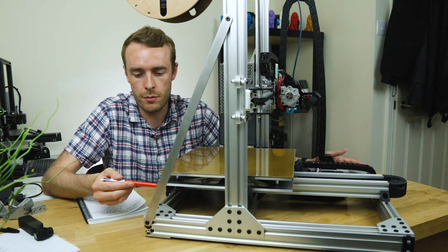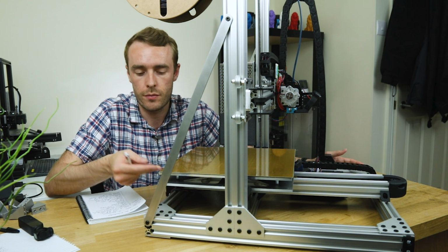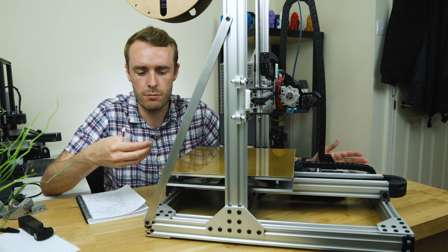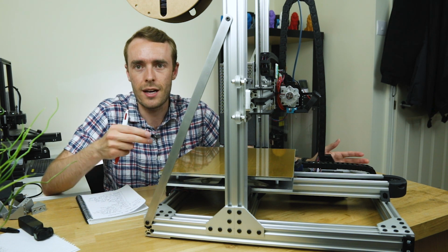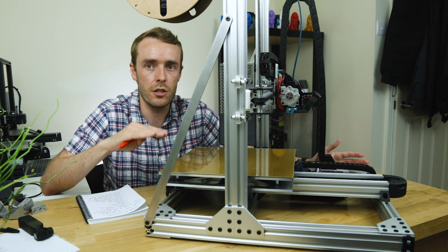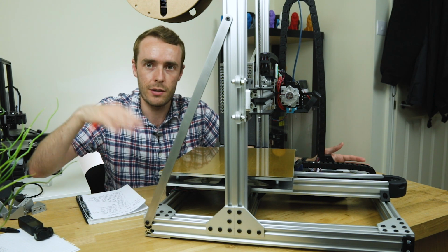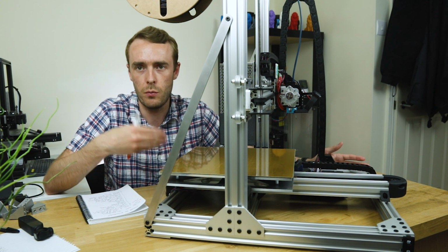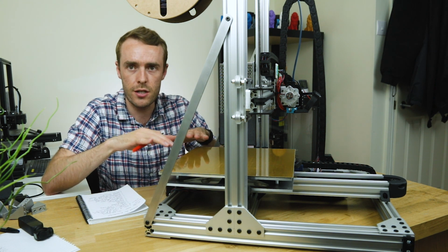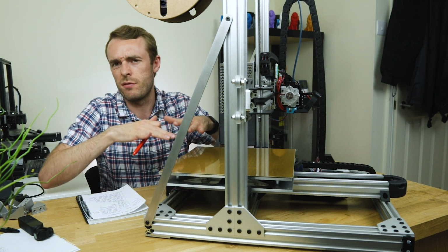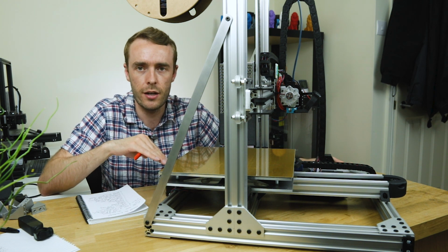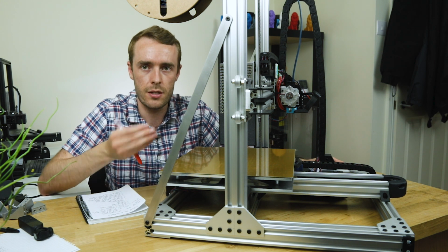So, 2 aluminium 6mm plates. The top one is probably the most important of the 2 in terms of specifying the correct materials. This 6mm aluminium is a milled plate, so it's cast and milled rather than being rolled, which means over time, as you thermal cycle, which means heat it up, cool it down, heat it up, cool it down, which you will have as a 3D printer with a heated bed, it doesn't warp. So it's not going to take residual stresses because of the rolling and end up warped one way or t'other or just strangely. So that's a problem we've basically eliminated by having a good material selection, which is this 6mm milled plate.